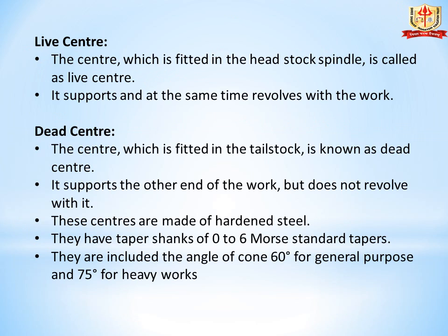Now we study what is the meaning of live center and dead center. First we study the live center. The first point is the center which is fitted in the headstock spindle is called a live center. The second point is it supports the work and at the same time revolves with the work. It is called a live center because it revolves with the work.